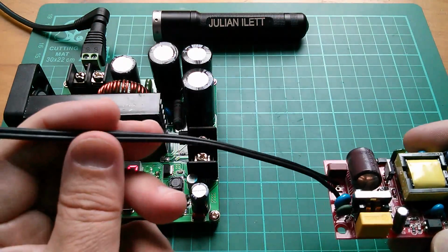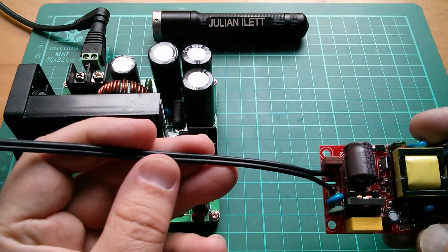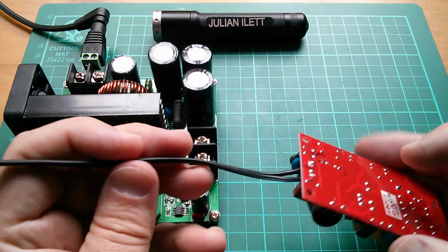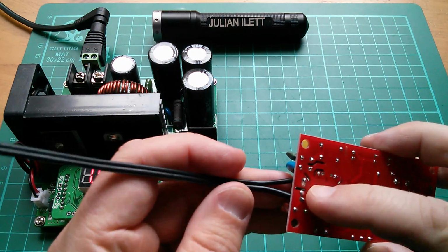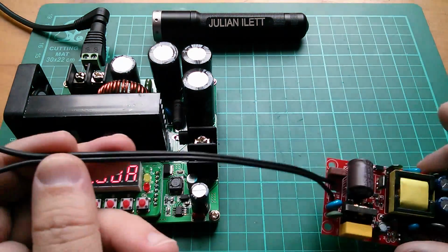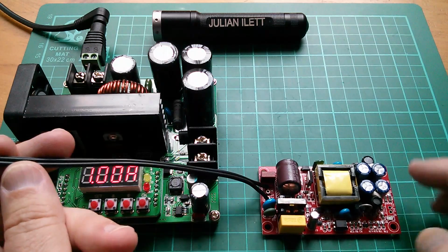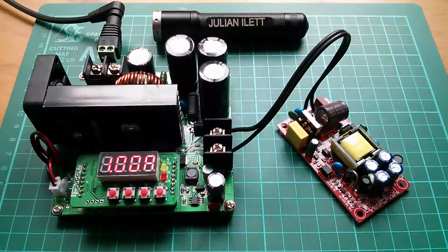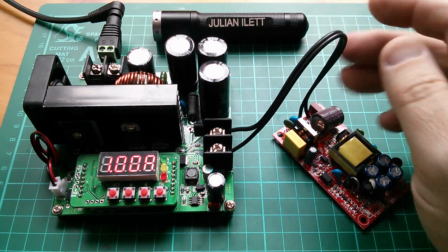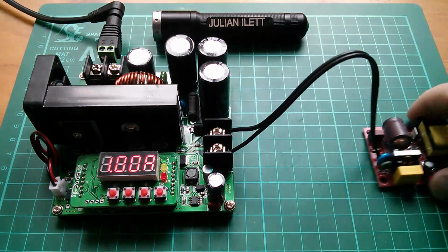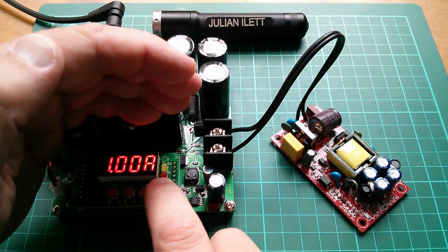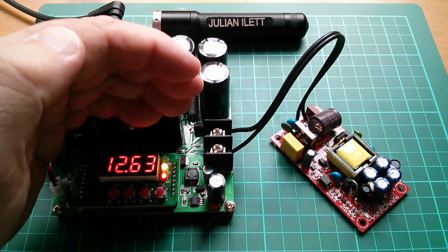Right, so I've attached this bit of twin flex, fairly low current, what we might have called bell wire in the old days. You'd use it for ringing up doorbells and that sort of thing. I've attached that to the power supply side, so I'm just going to strip this back and connect it into the boost converter, and then see if the little light comes on when we switch on the power. So there it is wired up. Now, I'm not bothered about polarity, so there's no obvious positive and negative markings here. I've just connected it whichever way around it fell. So now let's switch on the output to 115 volts and see if this powers up.